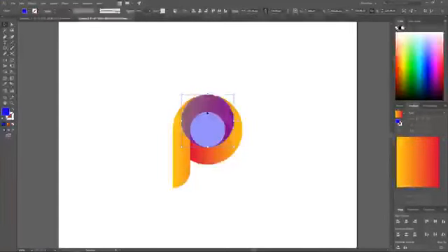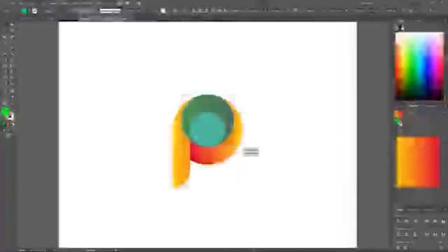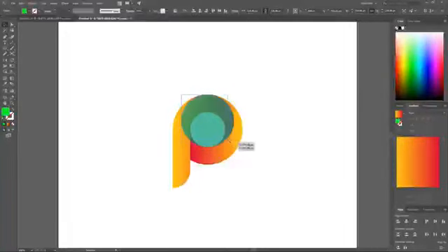And I'm going to create another copy of this. So I'm going to hold Alt and click to create another copy. I'll make this one green. And then I'll hold Control, grab this node right here, and snap it over to this node right there so it's lined up like that. And then I'll just click and drag this bottom right node down. I'll hold Shift and just click and drag it down a little bit, maybe about that much.